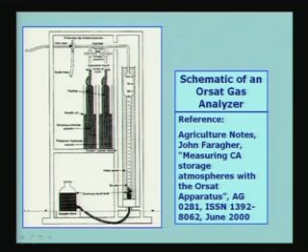So, you note down the reading here, and that will immediately give you this is 100, this is 0, and this will immediately give you the percentage of volume of the gas carbon dioxide in the mixture. Now, we have to close this and then open this and again transfer this gas to the other solution, the chromous chloride solution, which will absorb oxygen, and then again do the same operation of bringing it back to this